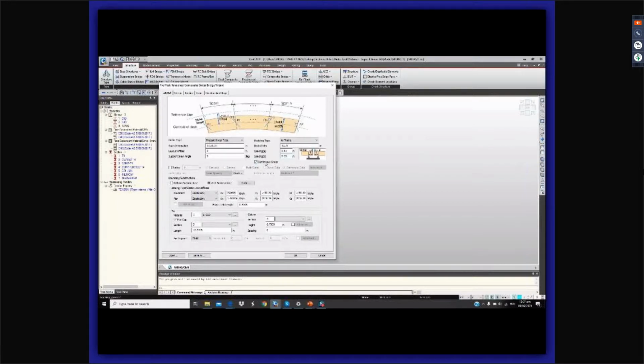And in the latest version, you have the option to check it either as continuous or non-continuous. Then if your bridge has some curves or is circular in layout form, you can check on the radius and then input the curve data or coordinate data of your bridge here. Then you can also input the substructure data of your bridge here. So let's check on the with substructure. Then here's the guide.